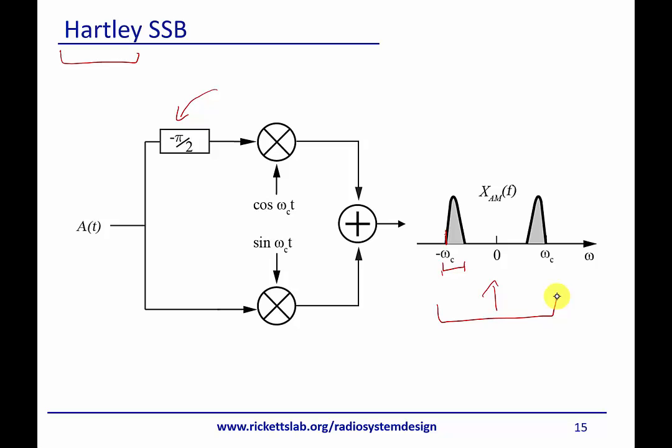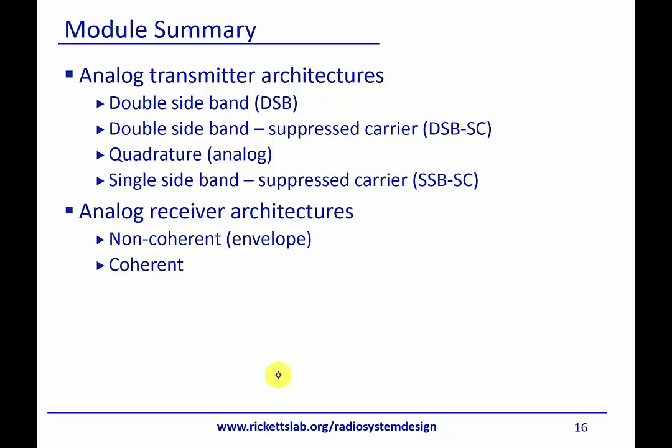And as you recall before, a coherent detector would simply bring that back down to its original carrier of, here's 0. Okay? All right, so that's it. We've covered the basics of analog modulation. The standard up conversion is just called double sideband. Double sideband suppressed carrier is where we made sure there was no DC offset. But remember, we like to have a little bit of a DC so we can get a carrier through to do coherent detection. We talked about quadrature modulation.